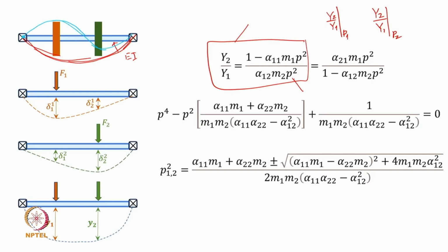So, the second mode will be this kind of a second mode, where when this disk is moving upwards, this disk is going to move downwards, and so on, right. So, then your y2 by y1 will be negative basically. It is quite similar to x2 upon x1 that we discussed for a 2 mass case with specific stiffness values. This turned out to be +1, and then in the next mode, second mode, this turned out to be -1. You remember that? So, those masses were moving in the opposite phase.